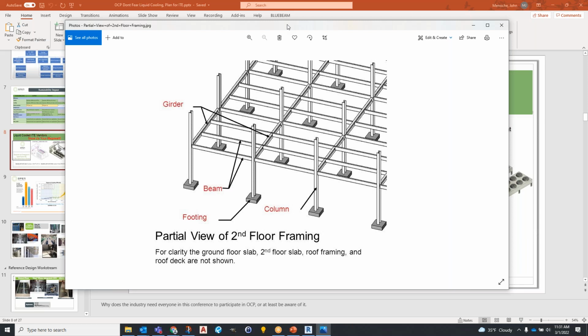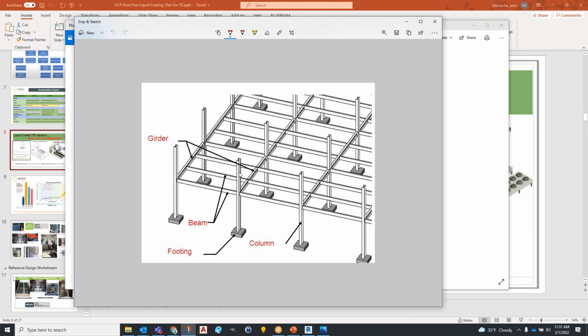Okay. So the way to think about this is that if you have point loads, the point loads need to be addressed. See, when you say design for a floor loading of, say, X pounds per square foot, you basically have covered everything. You covered the thickness and the reinforcement of the concrete slab. You've looked at the beams, the girders. You also looked at the columns, and you also look at the punch through strength of the column at the footing, and whatever else you do in terms of grade beams. So all of that is completely covered when you give a single number guidance, because unless all of that is satisfied, you can't say that it's 500 or 400 or 250.